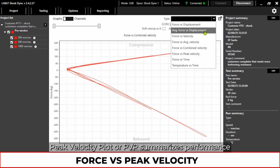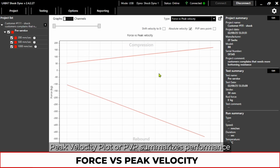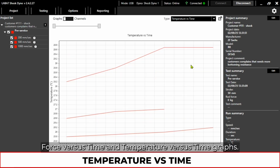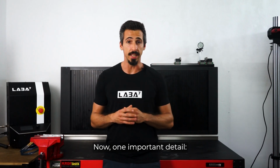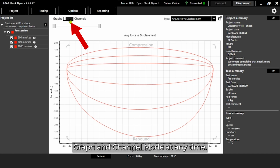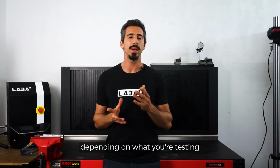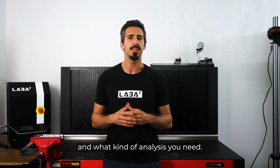Peak velocity plot, or PVP, summarizes performance across different speeds. It's especially helpful when working with interval-based testing or when you need a quick comparison of compression and rebound forces at peak values. Also, there are force versus time and temperature versus time graphs. Now an important detail. You can toggle between graph and channel mode at any time. These modes are interchangeable depending on what you're testing and what kind of analysis you need.